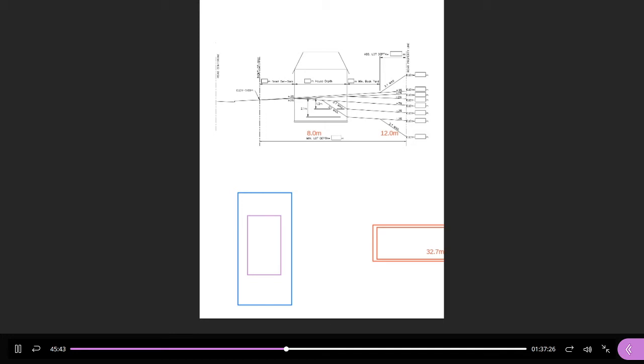So I'm going to use some hard numbers to do this calculation. I'm going to assume that the front is down at the bottom right. I'm going to put in a number here, 100. That's the elevation of the front lot corner right here. Now the drawing is exaggerated a little bit. The distance from the front of the lot to the front of the building is 8 meters. So let's put that in. This is 8 meters, going from here to here.